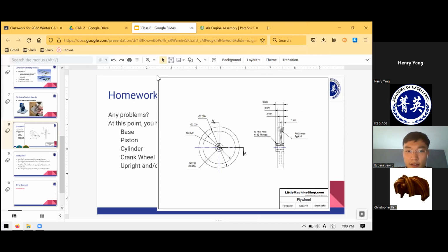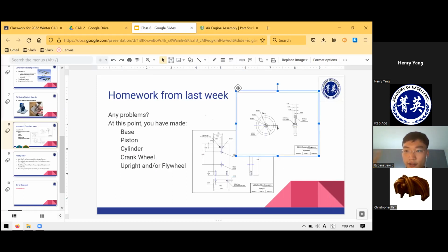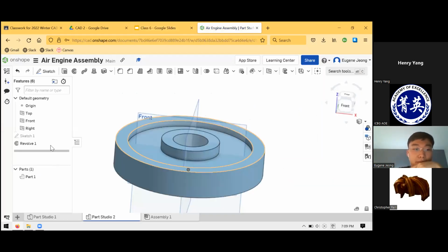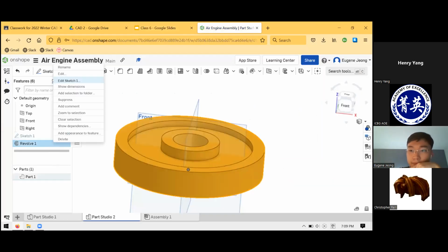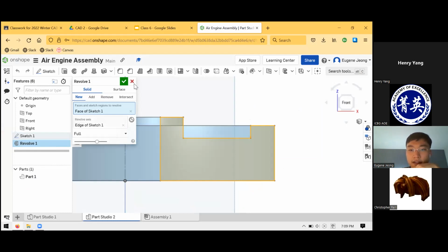Which surface do you click on to revolve it? The sketch profile is the eye that you drew, and the axis of revolution is that line. No, I'm saying when you revolve, which face of the flywheel do you click on? You're clicking on that I shape. Like the letter I, not the human eye, right? Mine didn't really click. Okay, eye, but yeah. Okay.